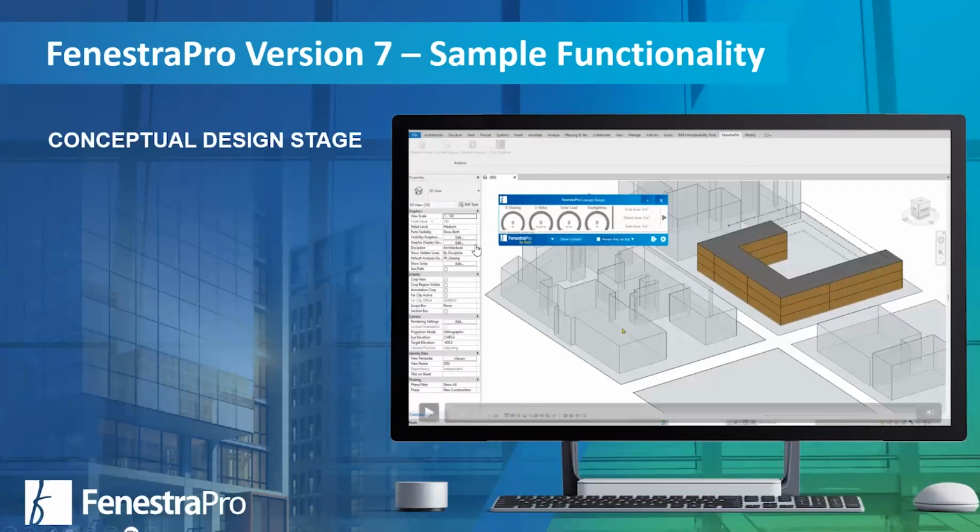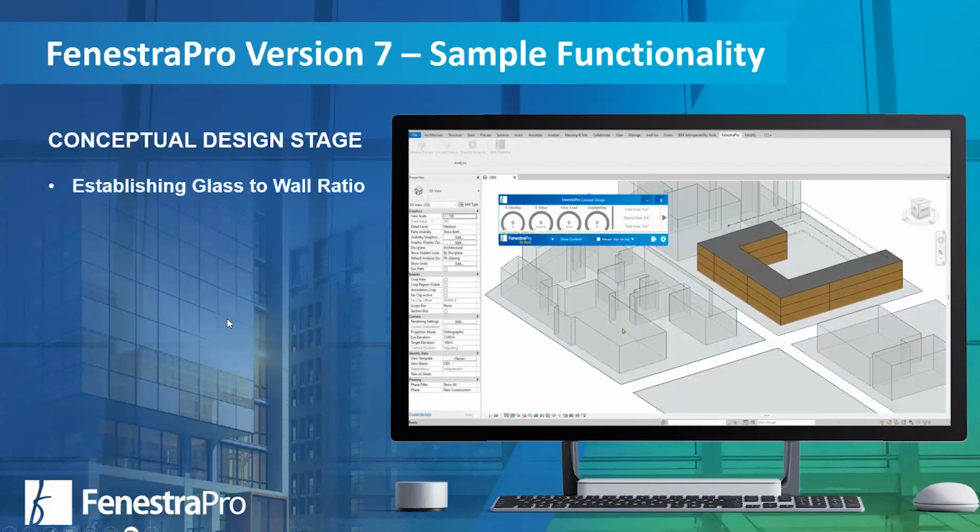course, thermal performance. As I said, at that conceptual stage where you've started to shape or mass that building, you can also model surrounding buildings and look at the impact that has on your distribution of glazing and the shadow effect or shading effect from those surrounding elements. But at that early stage, you can establish things like glass to wall ratio, the optimal distribution of glazing. So in other words, the best place to put the glass to maximize and control your heat gain across each